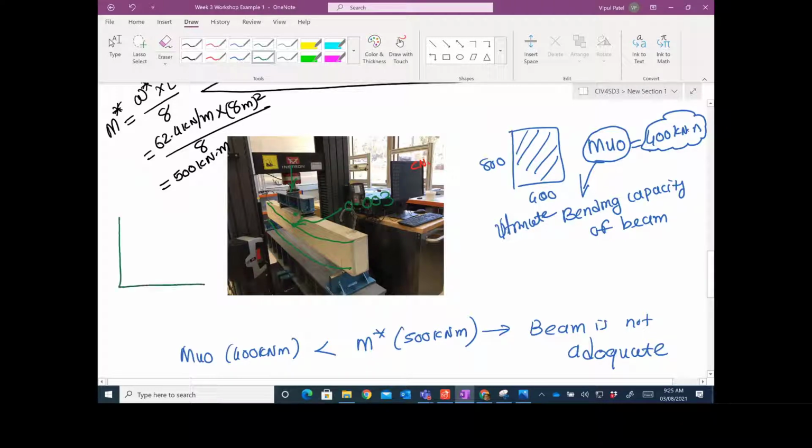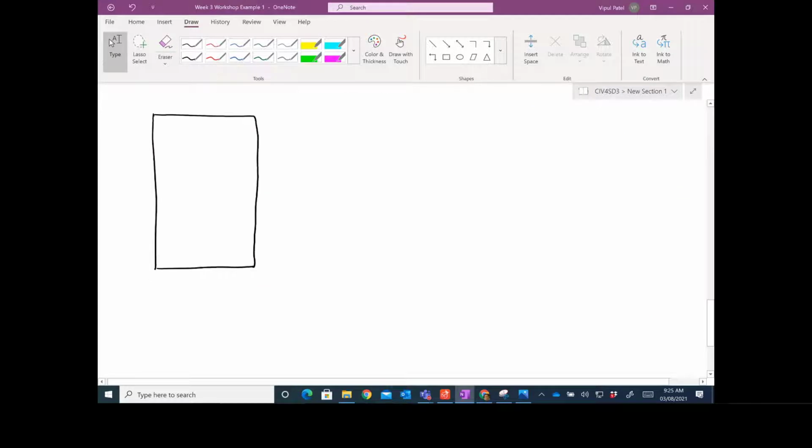So what if I draw the stress strain curve of concrete? If I draw the stress strain curve of concrete, after this 0.003, it will start dropping. This is the maximum strain that it will get. After this, your beam will not take any more load, it will just come down. And that is given in the standard.